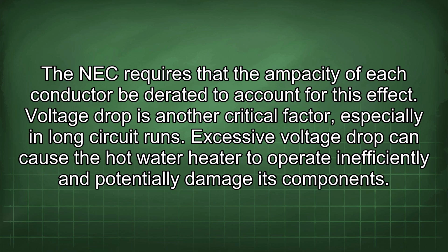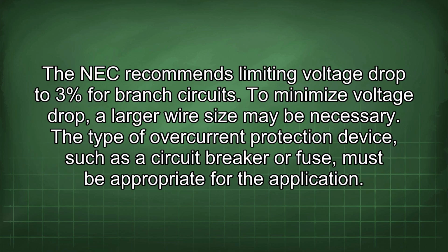Voltage drop is another critical factor, especially in long circuit runs. Excessive voltage drop can cause a hot water heater to operate inefficiently and potentially damage its components. The NEC recommends limiting voltage drop to 3% for branch circuits. To minimize voltage drop, a larger wire size may be necessary.